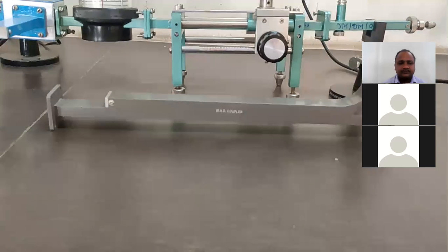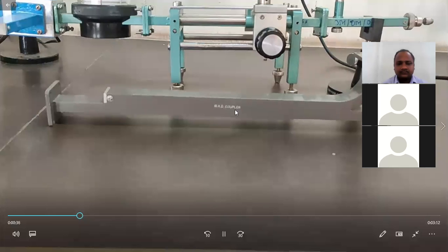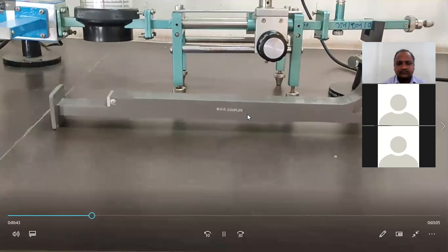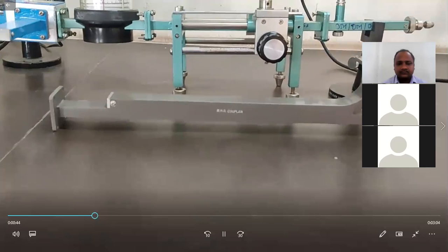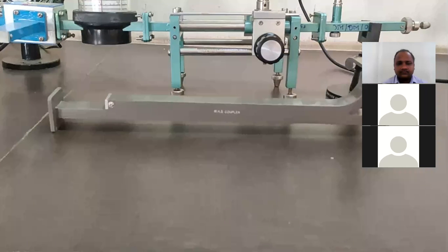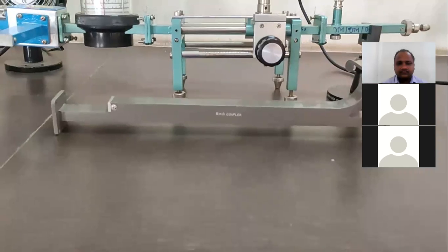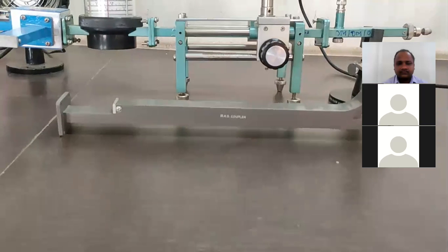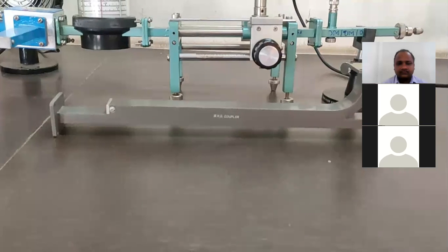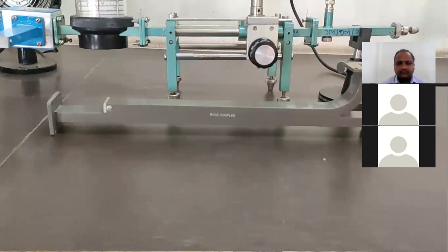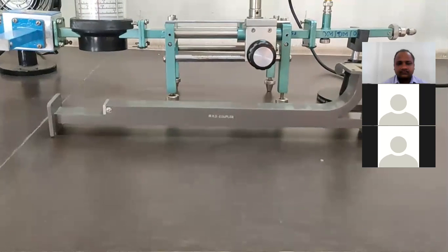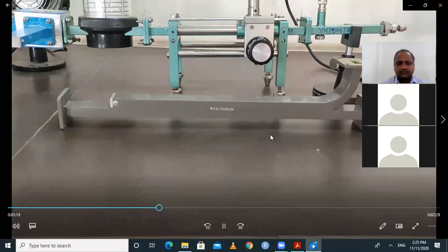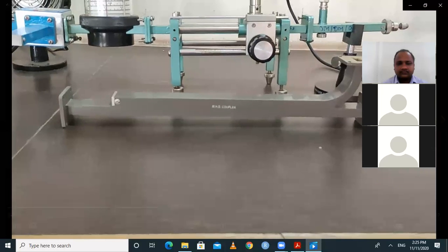And when we see the diagram or physical structure of the multi-hole directional coupler, it is made up of two waveguides. One is called the main waveguide and the other is the auxiliary waveguide. This multi-hole directional coupler contains two tiny holes, separated by a distance equal to lambda by 4. Suppose the input is given at port number 1, then you get output from port number 2 as well as port number 4, because the waves from the main waveguide are coupled to the auxiliary waveguide by the two tiny holes and pass from the main waveguide to the auxiliary waveguide. So we get some output at port number 4.